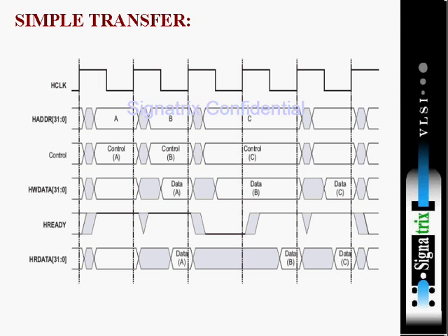And the first signal is address, and control signals. In control signals they comprise HSIZE, HPROT, HBURST, all those signals. We are going to see the detail of all these signals in forthcoming slides. Okay, I'm just telling control signals. And HWDATA, HREADY, HRDATA. So these are all the main signals, enough to analyze the simple transfer between the AHB master to AHB slave.